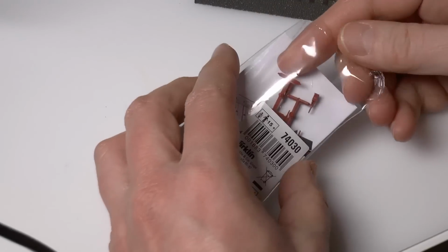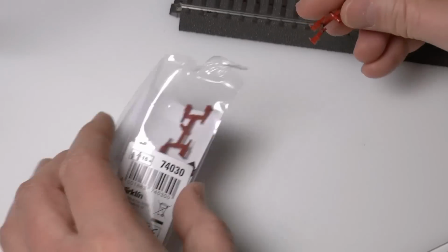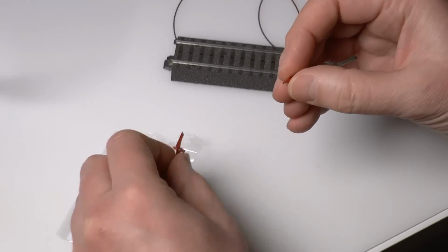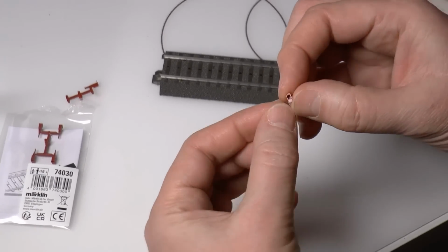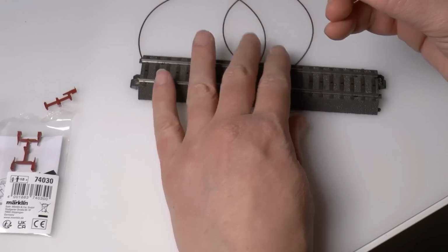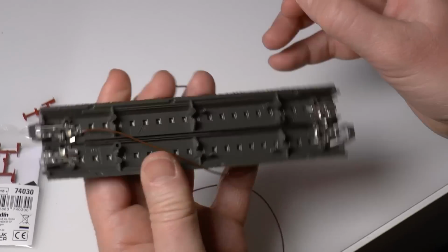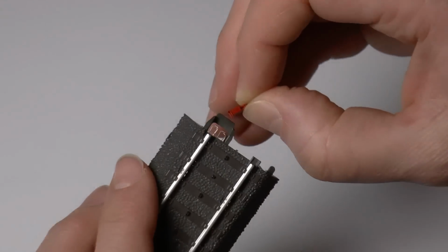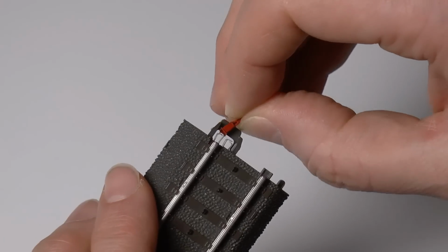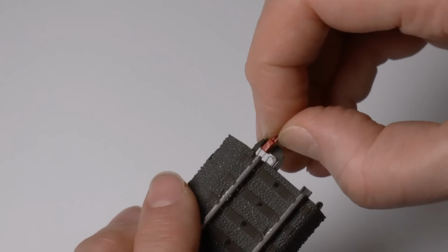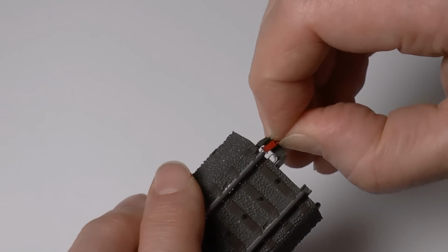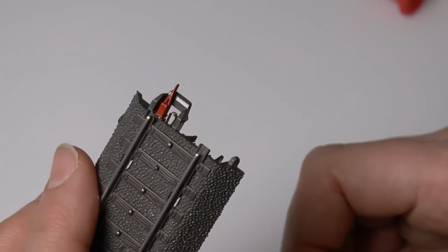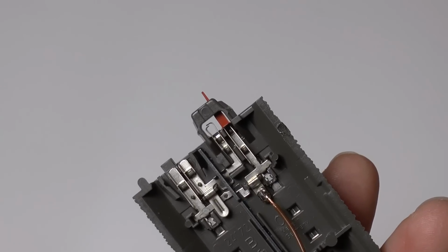You solder a cable to that contact blade, and then you buy these isolators and stick them over the contact blade in each end of this track, and voila, you have isolated that rail section you just soldered a cable to. So now when an engine, locomotive or a car rolls on this track, it will short circuit between the 2 rails, send a signal to the feedback decoder, and we know that something's there.